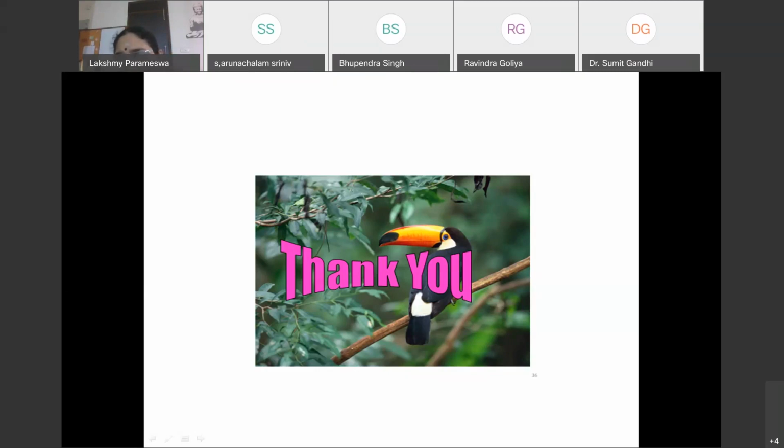Actually, for the design of bridges we have to consider various loads, and there are something like 19 of them. For all bridges we have to consider seismic, wind, and if they are in some water body, then the water current forces, all such things. Even the flood in the river also has to be considered. In some places it is the wind which is governing, and in some places it is the earthquake which is governing, but we can understand that by doing the analysis.